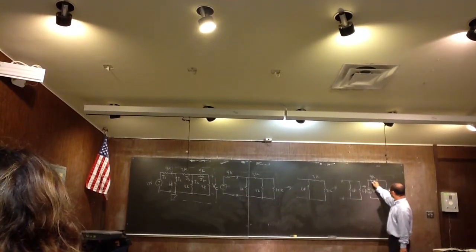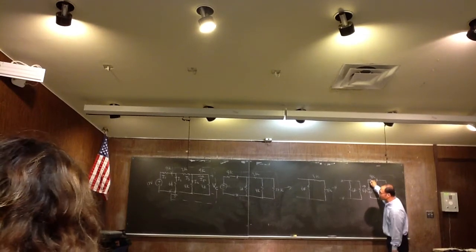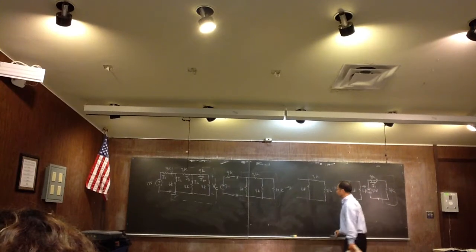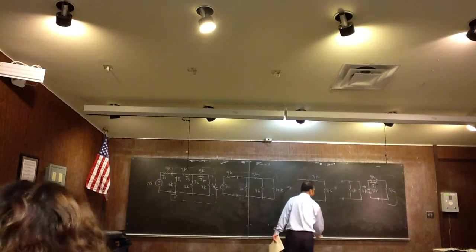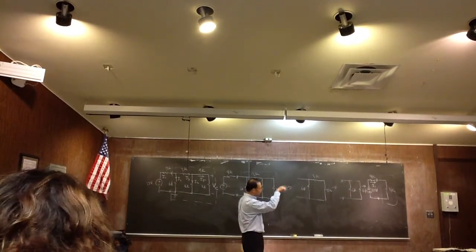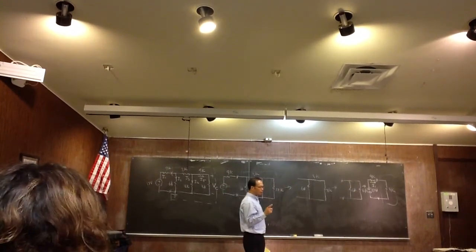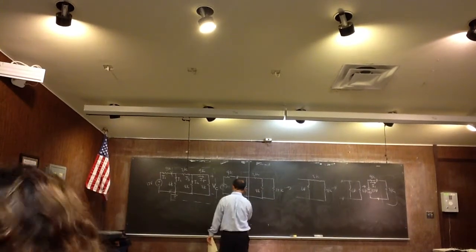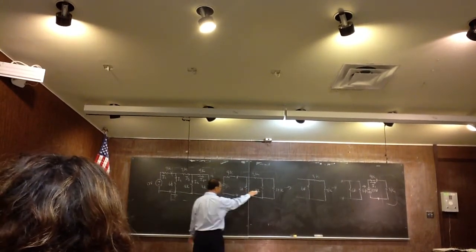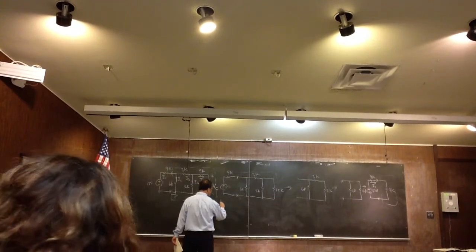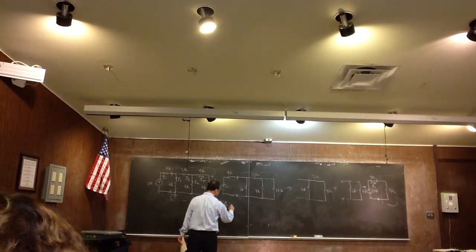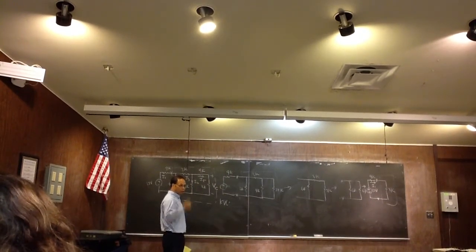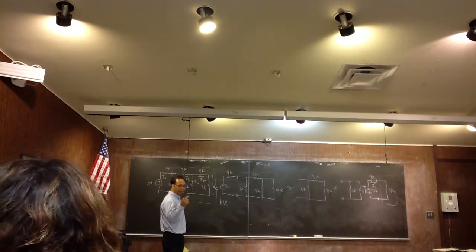Now we can try to find this current, which is labeled as I1. Okay, so how do you find that current? You have a single loop, so I can use the Kirchhoff voltage law, right? So I'm going to put the equation down here, okay? I don't want to erase that because I need it later. Okay, so based on the Kirchhoff voltage law, all the voltage rises and the drops, the sum of that is equal to 0, right?